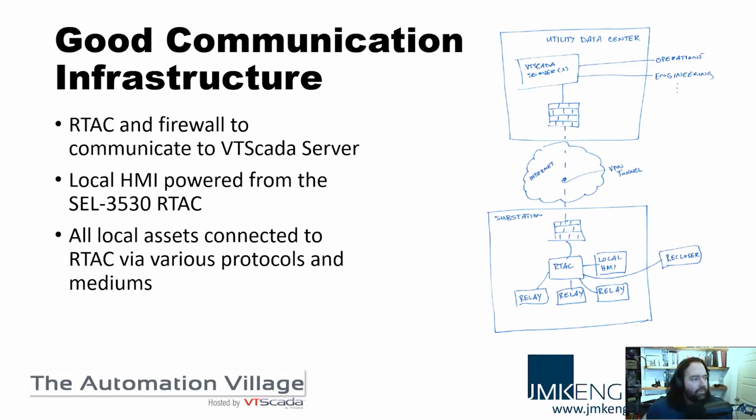All right, so now I'll get into a couple of the structures that you can use. My preference in general is, and because I'm a consulting engineer, I'm not representing any product, I can give you my suggestions. So I use VT SCADA for most of my historian and SCADA HMI applications. And I use SEL for my RTAC and protection relays almost exclusively. So in this example, we're assuming we have really good connectivity wherever the stations are, wherever the generation plants are, and it doesn't go down very often. Or if it does go down, the data that you're going to lose is not that critical.